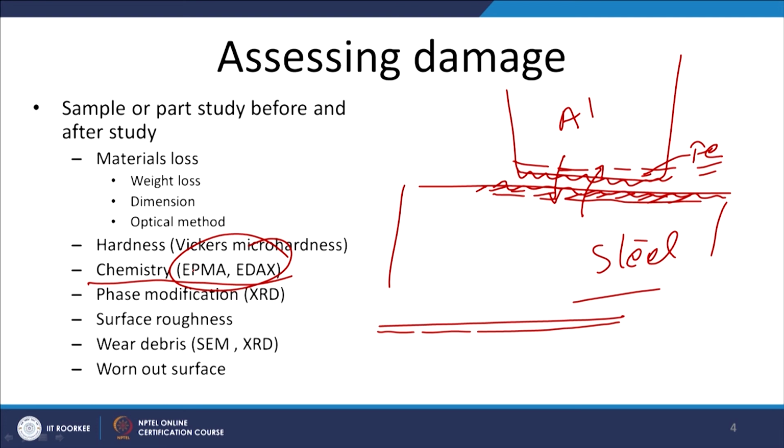At the surface layer, we will also see that these oxides are being formed. So, XRD analysis can be used to confirm the presence of these oxides, and if these oxides are present at the surface, it will suggest the presence of mild oxidative wear, because in mild oxidative wear both the metals involved get oxidized. Removal of these oxides will be responsible for wear, but their presence at the surface will be confirmed by the XRD phase analysis, which will indicate that mild oxidative wear was responsible for loss of the material